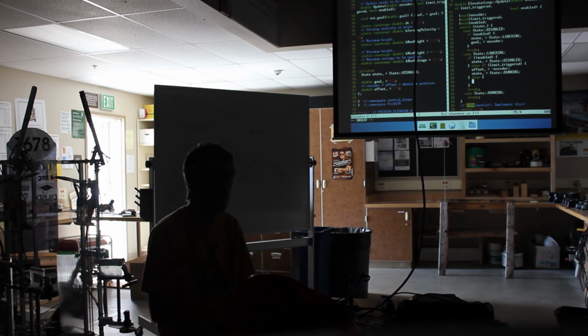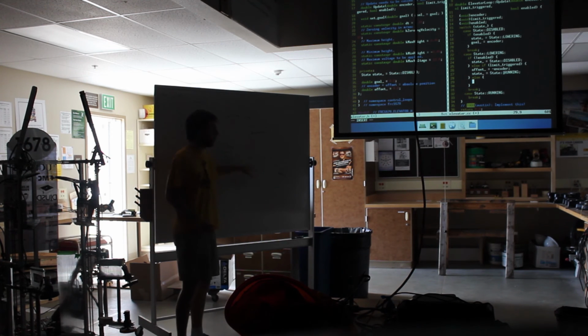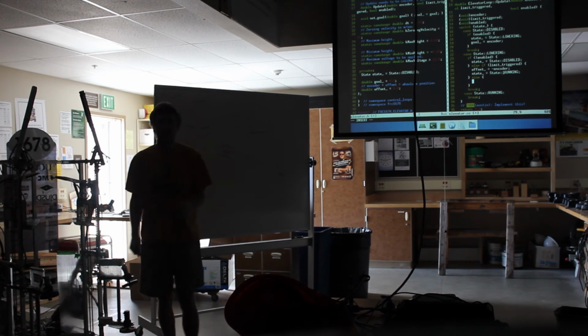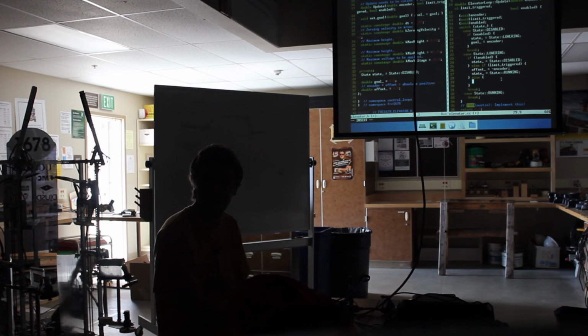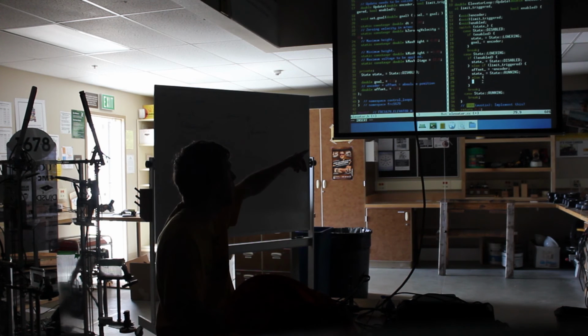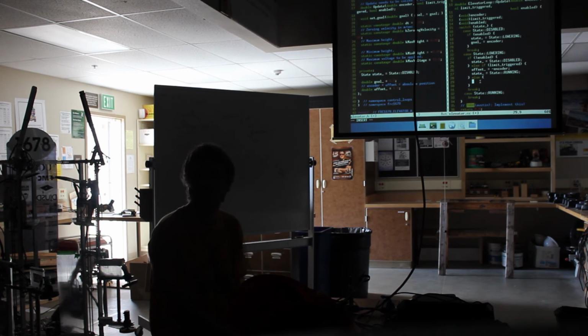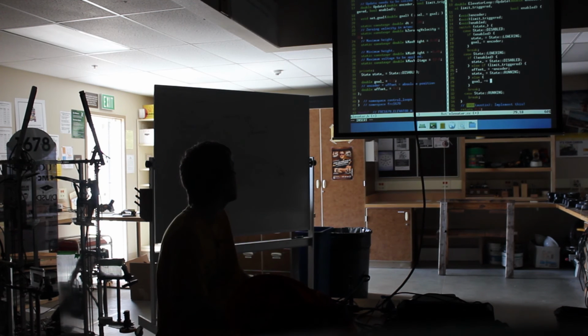Otherwise, we want to move down slowly. How do we do that? Give the motor a certain voltage? But for our output, we want to let the control loop do that. We want to generate a goal here. So how do we generate a goal that moves down slowly? Whether or not it sees that value, like the Hall effect. Sure, so that's deciding our edge transitions. But if we don't see it yet, we want to tell it to go down a little bit. So that's going to be an if. Yeah, if it doesn't see the Hall effect, keep going. Okay, and how do we keep going? Goal minus equals zeroing velocity times dt.